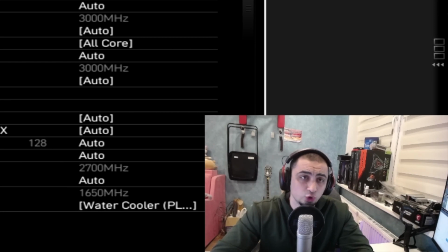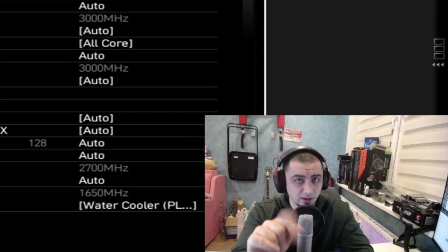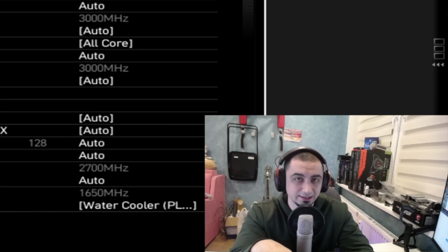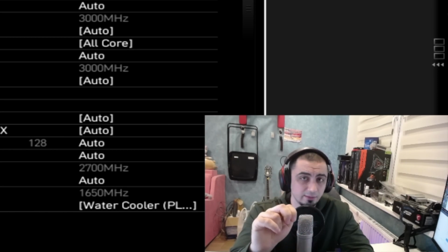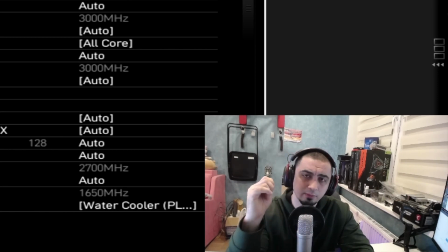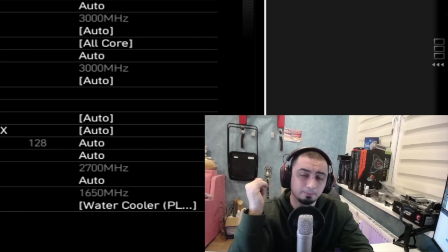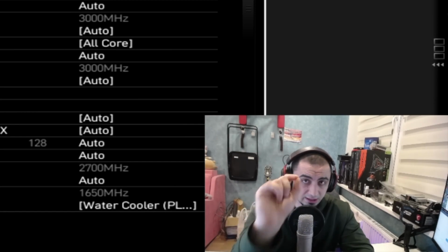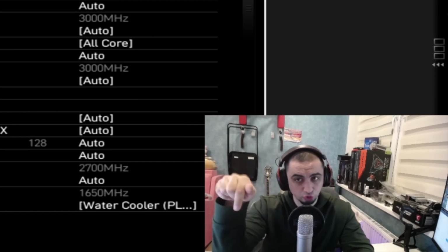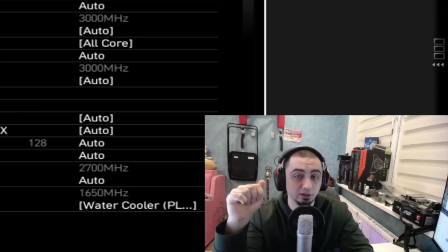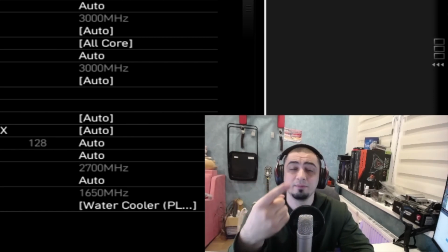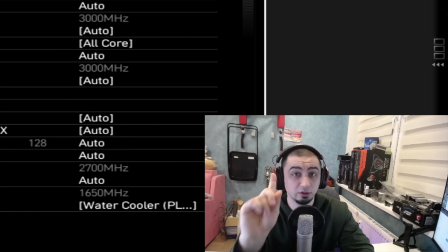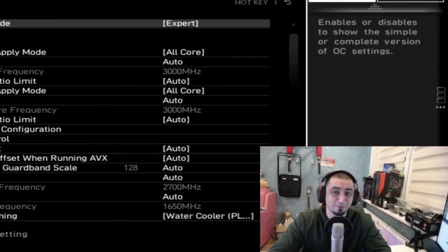And if it does not help, then look in the instructions for your motherboard, where clear CMOS is located. These are two pins, you need to short them to each other. This can be done with a metal object, or you can pre-connect the reset button if you have it on the case or separately. And the next option is when your PC is completely de-energized, we pull out the battery for about a minute. Do not forget to put the battery back in. After that our computer will turn on.